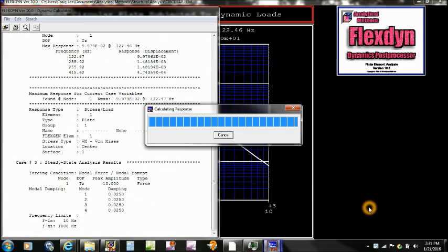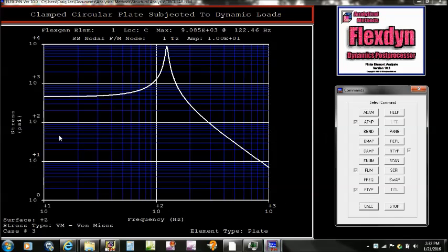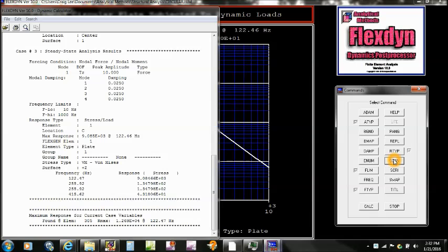So I'm going to hit calculate there, and it does the analysis, gives you the information about what we're looking at here, and we have about 9,000 psi of stress at that extreme fiber there. So now here though, I can hit scan again, and it'll look for the highest von Mises stress in all the elements under the given condition. So we'll hit scan there. It comes back and tells us that element 305 has about 12,700 psi of stress, and that's the highest that it found.